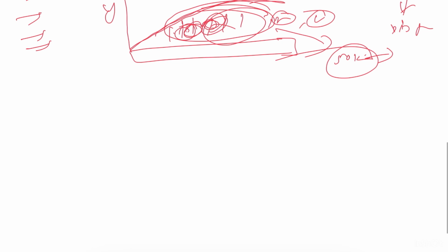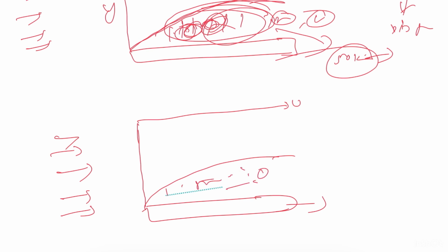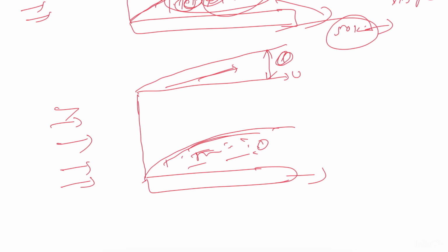In the same manner, this is the boundary layer, this is the solid plate, this is the free stream velocity. The losses of momentum in this boundary layer zone will be covered by fluid flowing in this zone theta. This theta is called momentum thickness.